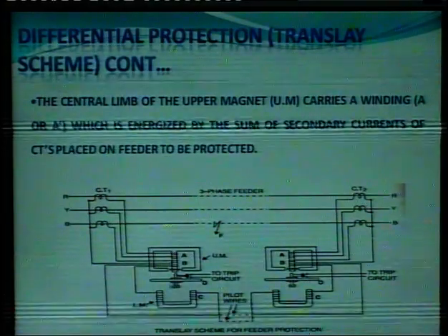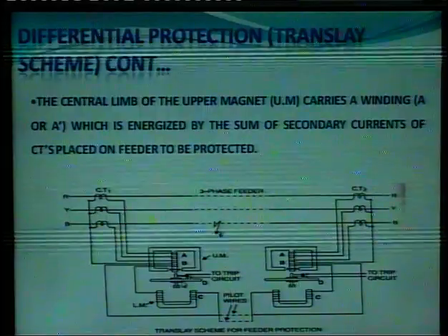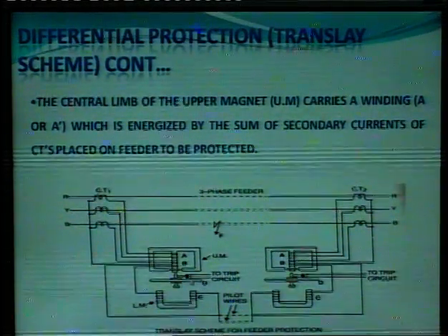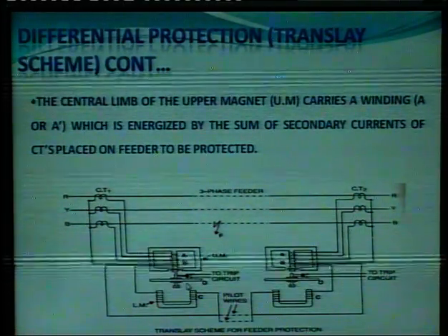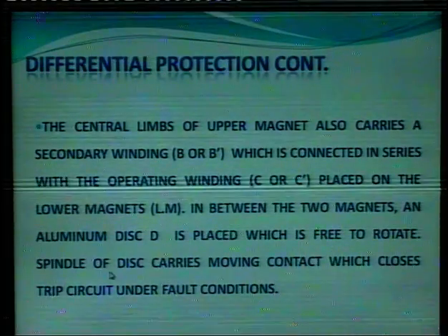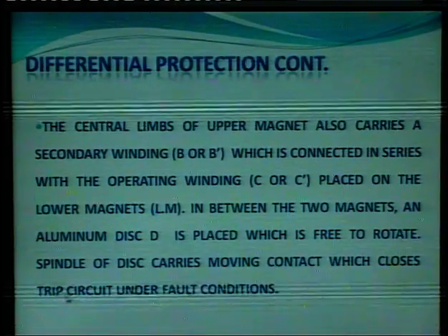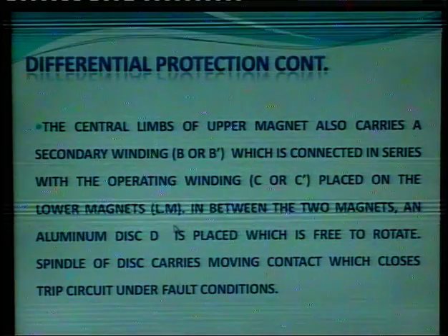Whenever EMF is induced in this disc, it is free to rotate, and when it rotates, the contacts of the trip circuit get closed. The spindle of the disc carries a moving contact which closes the trip circuit under the faulty condition.